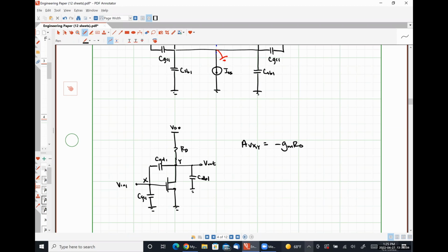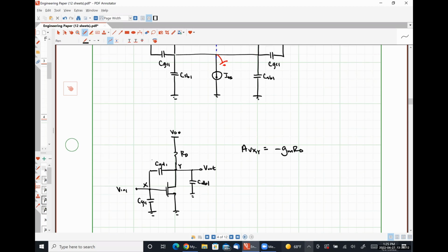Okay. So despite the fact that we have this big ugly circuit, because it's perfectly matched, effectively all of the poles on the left-hand side and all of the zeros on the left-hand side are going to be exactly the same as all of the poles on the right-hand side and the zeros on the right-hand side. So from a high frequency response, it's going to behave identically to a common source amplifier, which we spent literally over a week describing.